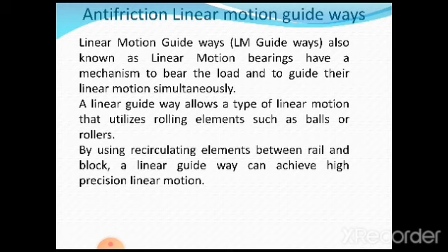This can be done either by friction guideways or by anti-friction guideways. In between the moving element and the stationary element, we use the balls or the rollers. That means there is no direct contact between the moving element and the stationary element.